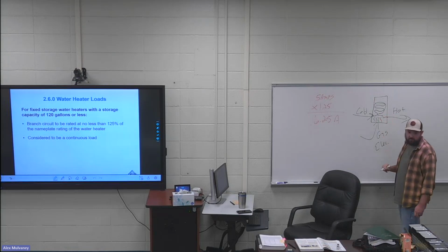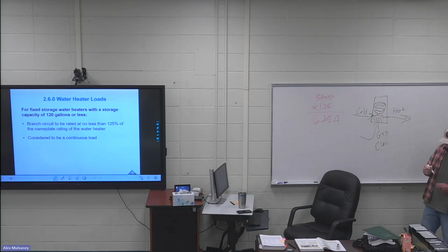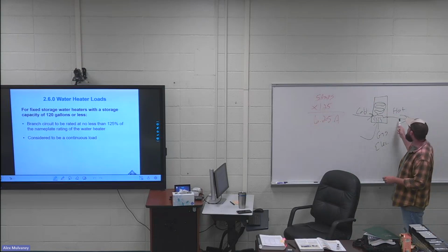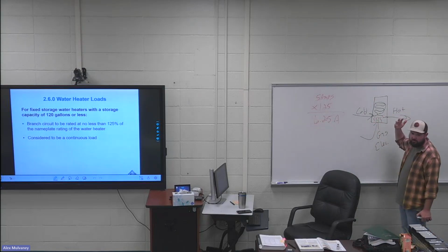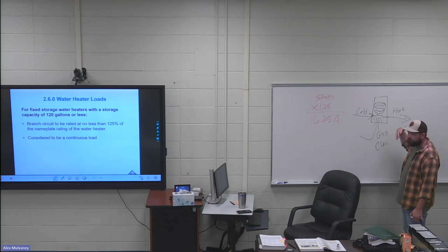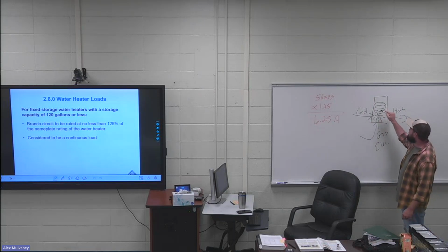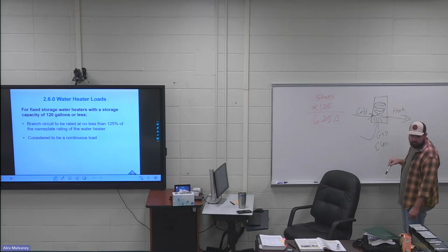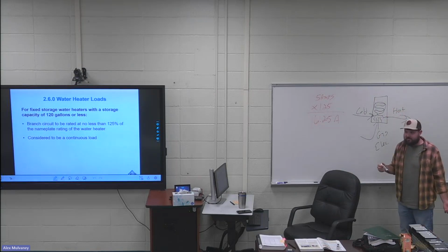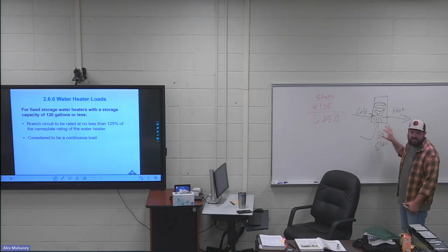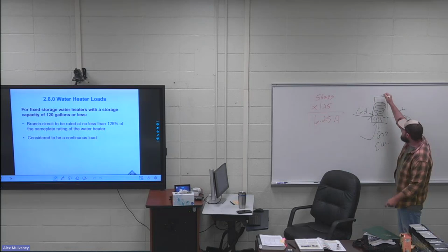They're often on garages and stuff like that. Yes, so that puts heat in it. Whenever I turn my water on this side, water's flowing through this. It kicks on the circuit and tells the gas or electric to start heating up. As the water goes through, it gets hotter and hotter the further it goes, right? That's how a tankless water heater works. This is a non-storage type, right? This would be tankless.